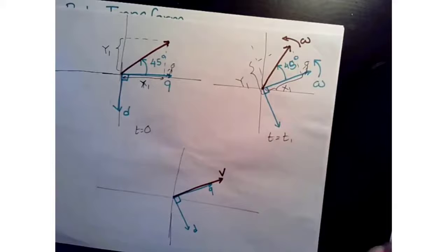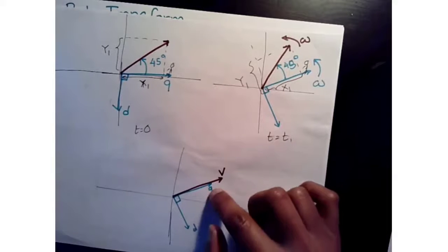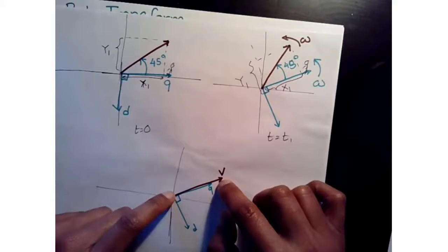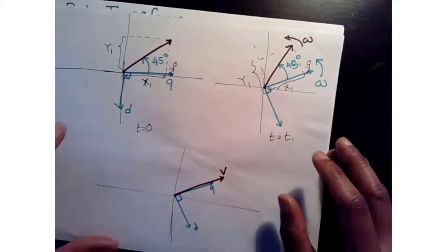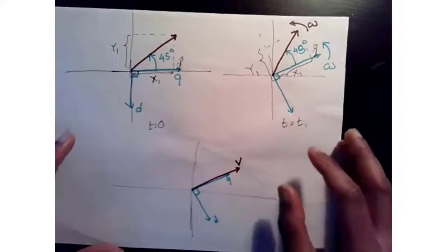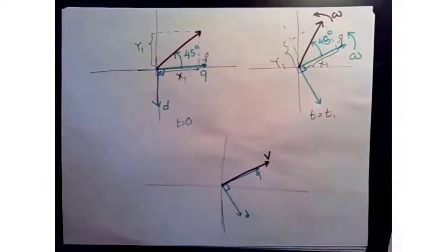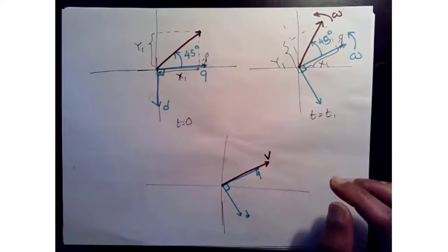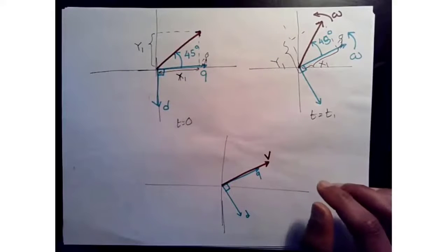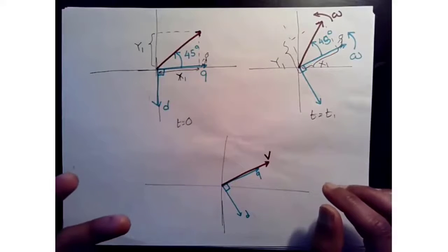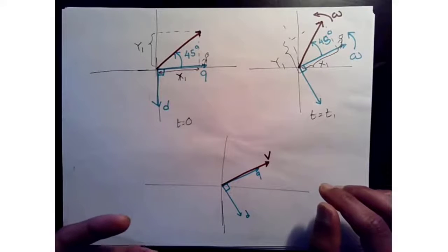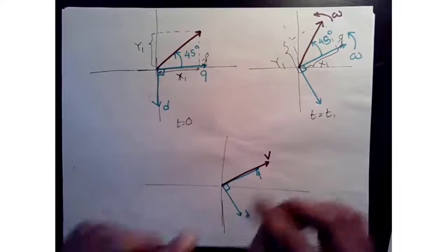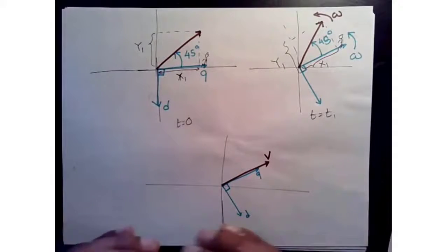The importance here is when you are aligned and rotating at the same velocity. For synchronous machines, this gives us an advantage because you can observe your machine variables from this rotating frame. Because all of your currents and voltages are at synchronous frequency, you will see your variables as DC.